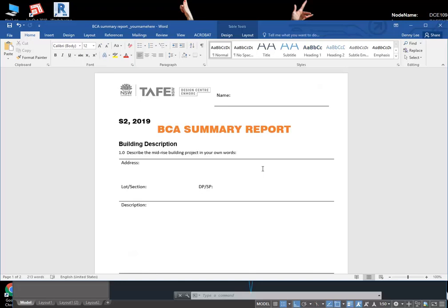No, this is the upper level, isn't it? Yeah, it's open to the ceiling. But this is all solid around here. That's wall and that's glass. It's only if you want these to be windows that you've got a problem. I can change it. I mean, the simple way would be to make it more solid. Otherwise, you can have windows, but you need a vertical separation between the unit below and the unit above.